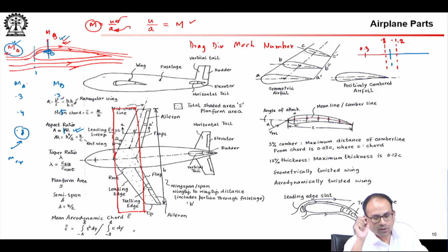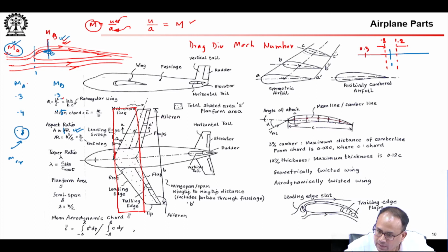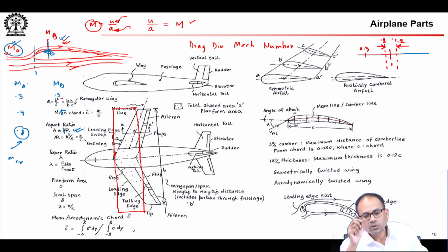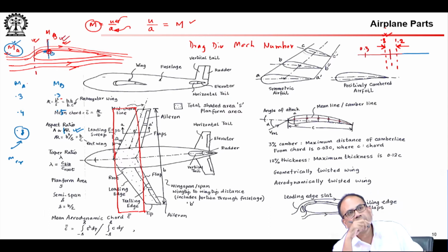It does not need to be 0.8 and 1.2, it can be ballpark away from those numbers. This window was called transonic, and part of the reason is this region. So, this vehicle is now flying in the transonic window, where although the free stream Mach number is less than sonic, there are portions on the wing that have reached sonic speeds. That is why something like 0.8 is the beginning of the transonic flow Mach number window.